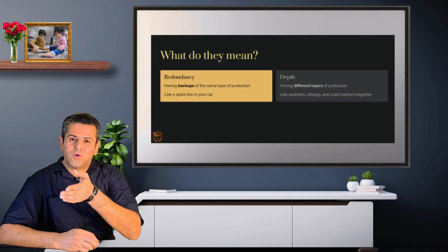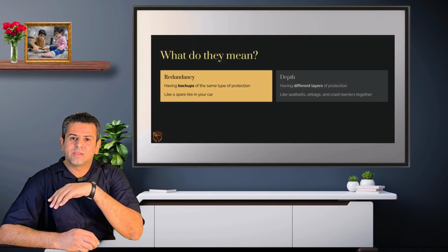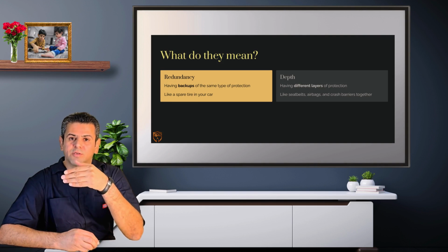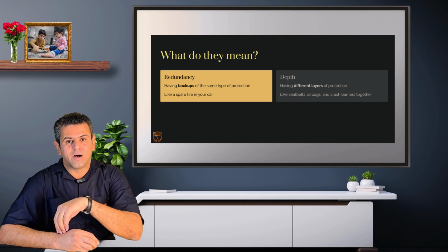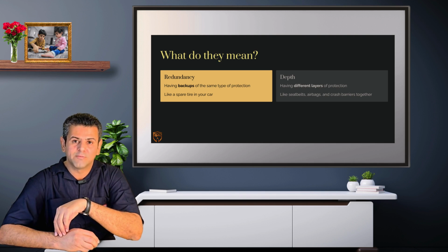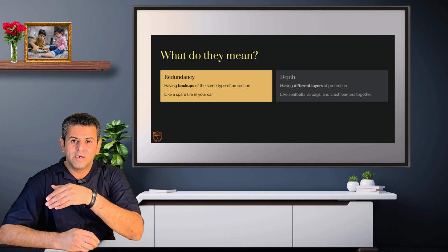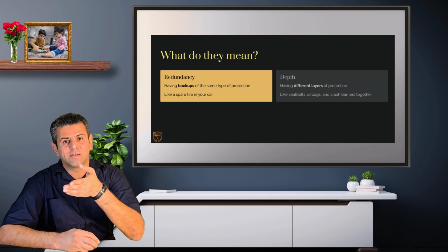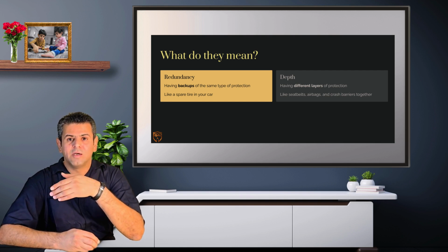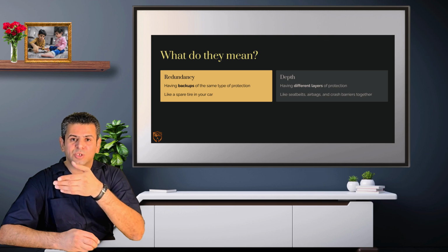The takeaway for the audience is that good process safety is about redundancy and depth, never assuming one barrier will be enough. This also illustrates why PSM has multiple elements. Each element addresses a different slice of safety. For example, training addresses human performance, while PHA addresses design hazards.